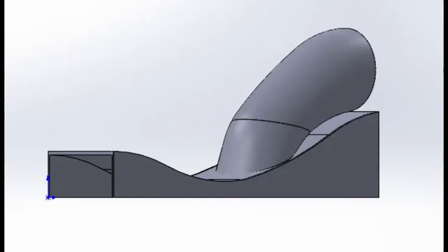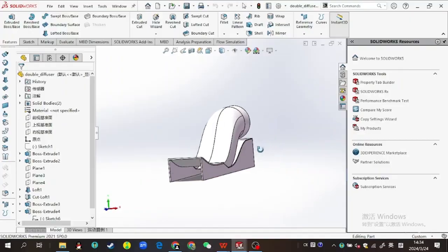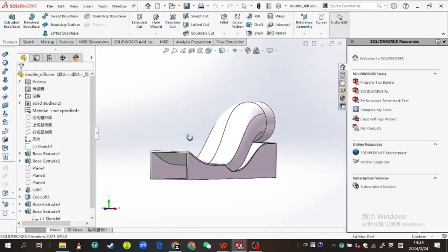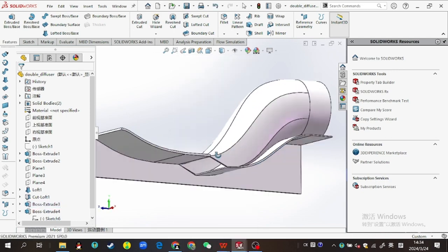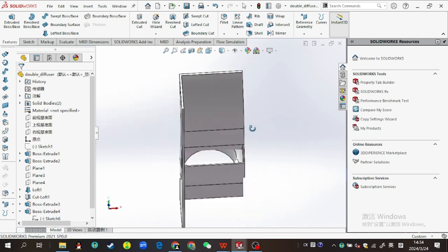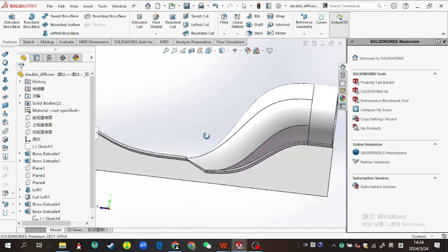Despite the failure of the first design prototype, the Venturi tunnel can be derived into a double diffuser type, with the upper diffuser incorporated with a ducted fan so that it could avoid the turbulent air generated by the fan from going into the tunnel and casting a negative impact on the clean airflow in the tunnel. Here's a sample double diffuser type. As you can see, there's an inlet directly connected to the upper diffuser, which is used for accelerating the airflow in the duct using a ducted fan.